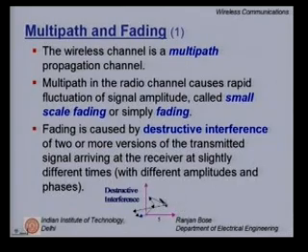But when you add them up vectorially, you get something very different from what you send. In fact, most of the time the interference is destructive. That is, what you receive back is much lower in amplitude than what you actually send. So a lot of large vectors add up to a small vector. This is our primary enemy, and we have to overcome the effects of fading.